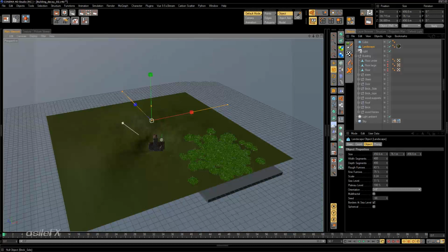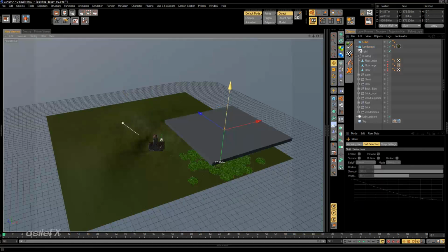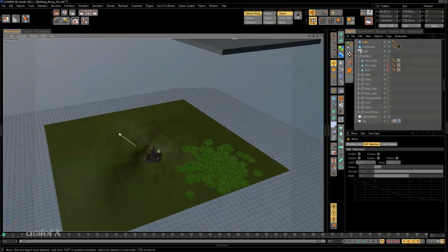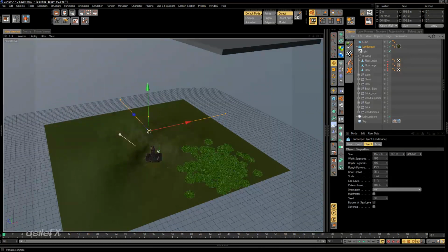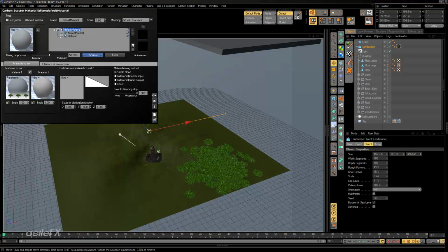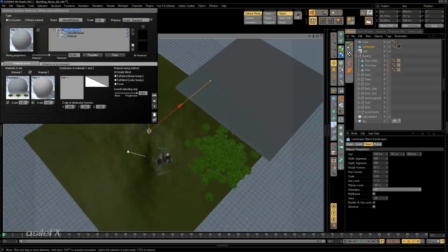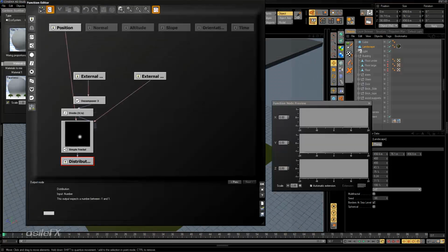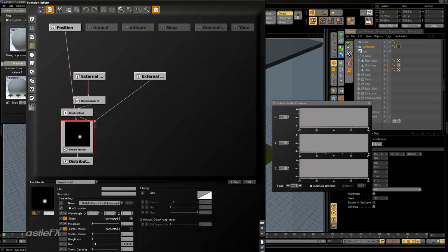So we should be able to take the cube and move it pretty much anywhere we want. So up here, before it wasn't showing, go to populate objects, populate again, and now it's still going to show. So the wavelength, just by setting that to 0, it makes it null. So it's basically a flat plane, and no longer takes into consideration the origin of the Z and the up and down axis.